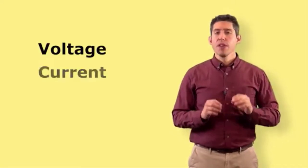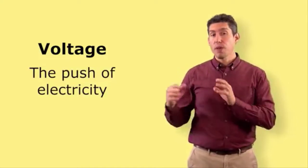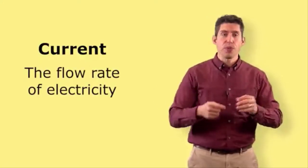Now that we know how to measure the solar input, let's begin to look at how we measure the electrical output from a photovoltaic module. Photovoltaic cells produce electricity, and we have to be able to measure that in some way. There are two fundamental units that we measure for a photovoltaic module to begin to figure out how much power it's producing. One of those units is voltage, and the other unit is current. Voltage is thought of as that push of electricity, how hard the electrical motion is pushing from one side to the other side of the module. Current is thought more of like a flow rate, or how fast the electricity is moving through the wire.